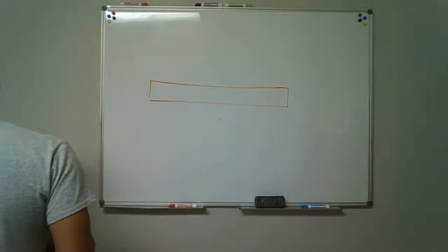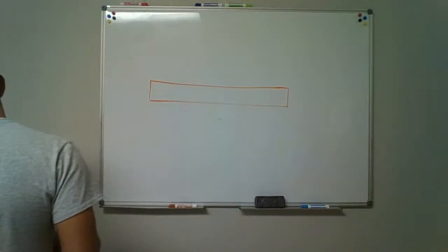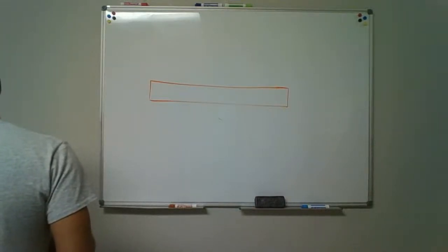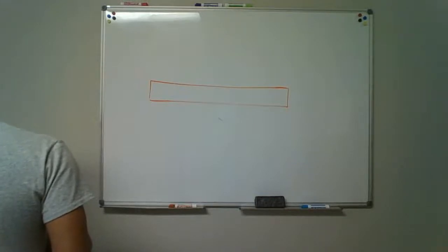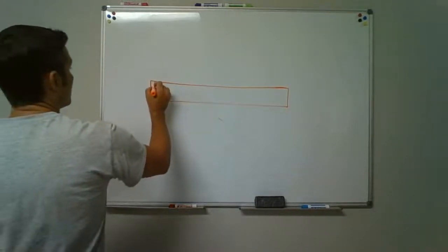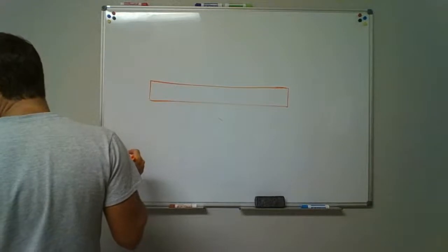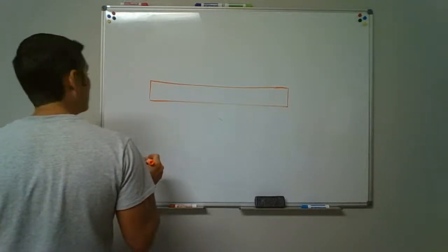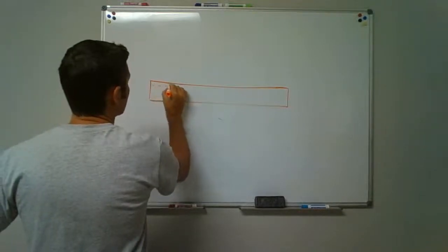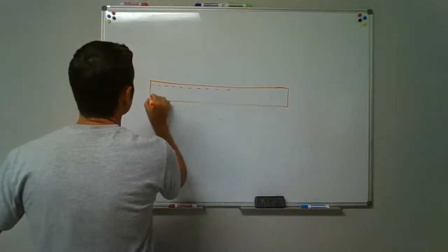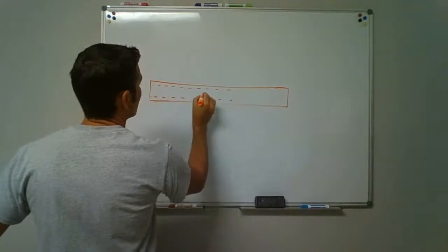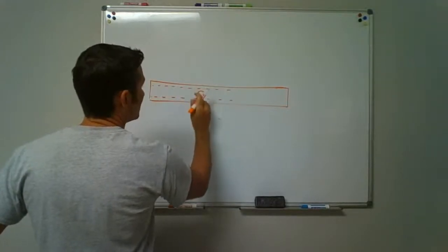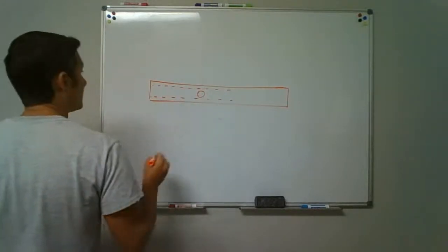It says notches on the ends of the joist shall not exceed 1/4 the joist depth. Okay, so notching it can't be more than 1/4. Holes bored can't be within the top or bottom 2 inches. So take off the top and bottom 2 inches. The holes have got to be somewhere in between there, not into here.